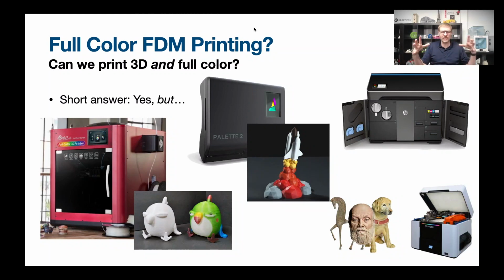They take sheets of paper and cut each sheet to the shape of the layer of the object, then glue the sheet, and then color around it using an inkjet method, much like the Da Vinci. They build your object by stacking pieces of paper cut out in the shape of the object, so you end up with pretty high quality color 3D objects.